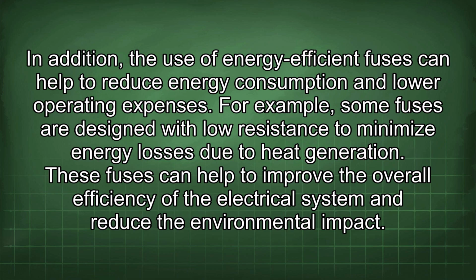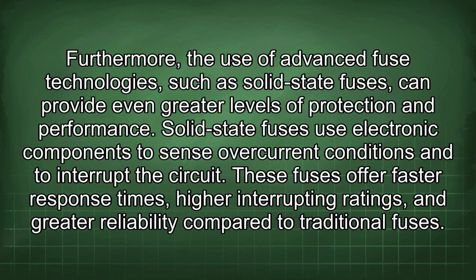For example, some fuses are designed with low resistance to minimize energy losses due to heat generation. These fuses can help to improve the overall efficiency of the electrical system and reduce the environmental impact. Furthermore, the use of advanced fuse technologies, such as solid-state fuses, can provide even greater levels of protection and performance. Solid-state fuses use electronic components to sense overcurrent conditions and to interrupt the circuit.